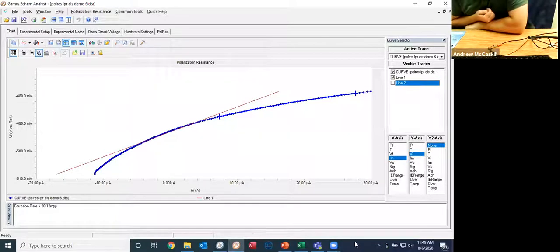But when you say LPR is destructive relative to EIS, if you ran LPR constantly on the same sample over and over again, then yes, you're eventually going to corrode the system. But if we're only applying 15 millivolts on either side of OCP for just a minute or two, then, as I said before, it's an active experiment. You're perturbing the system, but I wouldn't say that it is fully destructive. It's kind of in a gray area.